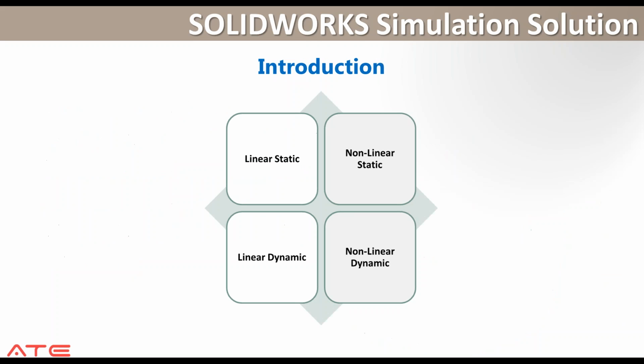So, a quick introduction. What is FEA? I categorize it into four boxes. Starting with the most basic and easiest to understand is the linear statics. And then we have non-linear statics, due to certain characteristics of the materials or the behavior of the structures. Then we have linear dynamics, where we start considering huge movements or dampings or inertias. Non-linear dynamics is where we cater for non-linear materials.